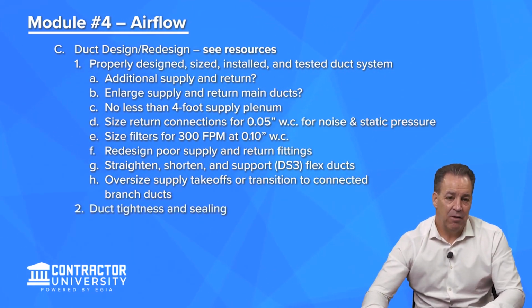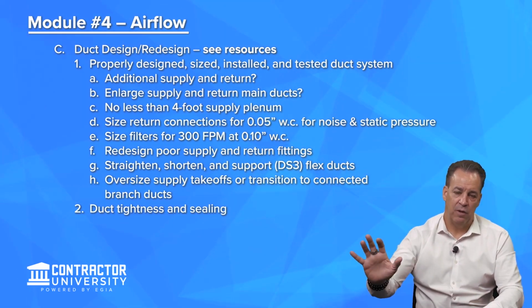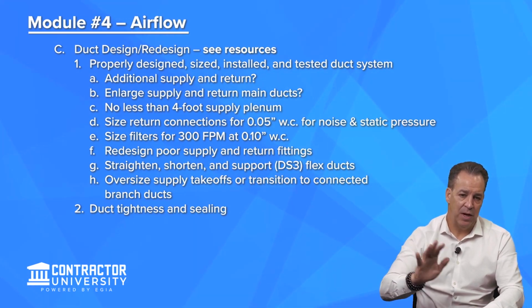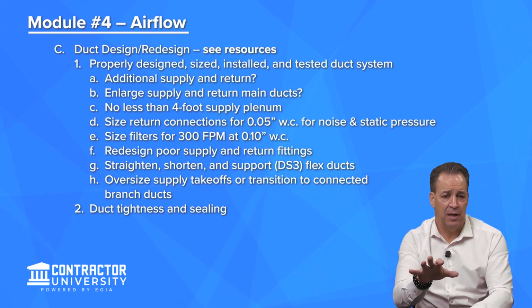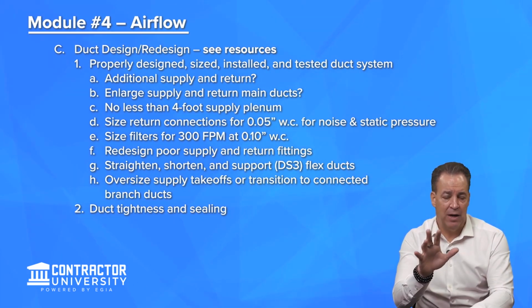Duct tightness and sealing. You're going to inherit a duct system that's going to be leaky. I guarantee you, if you just walk around and you should crawl the entire duct system in the basement, the attic, or the crawl space, or the garage, or wherever it's located, wherever you can access it, go ahead and look at every joint, every seam.